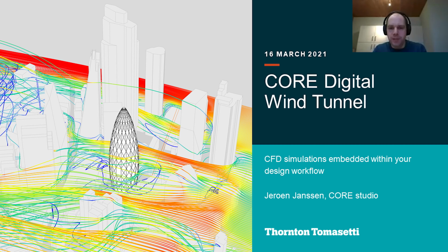Interesting question. As detailed as you want, I would say. So the person is thinking of a project condition where a perforated brise-soleil was about 1 meter in front of the curtain wall and clearly provided some level of wind blockage, but building codes don't have much guidance on allowing reduced wind pressures on components and cladding.